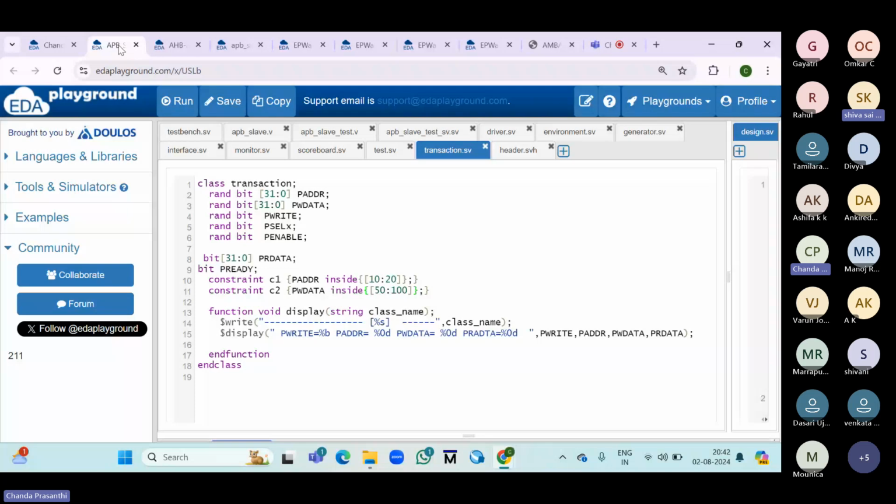So without confusion and complexity, because in SystemVerilog we use hundreds of signals, to avoid that we simply use the logic data type in place of reg and wire data types. Okay. Yes, ma'am. And can you tell me what is the difference between integer data type and int data type?